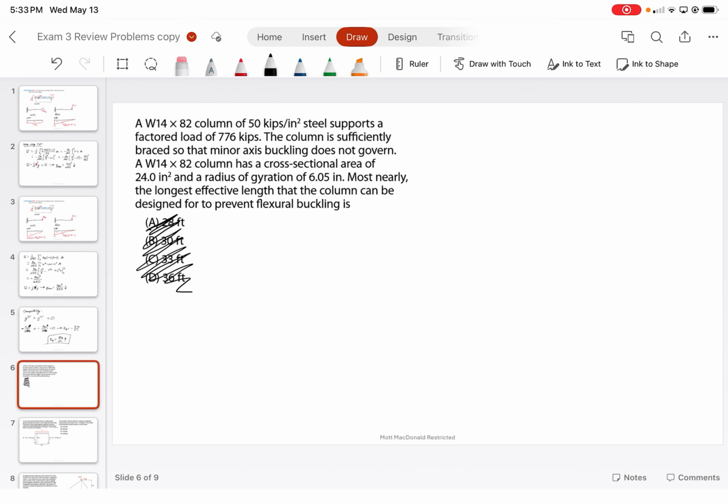But still, that seems very low, the K. I don't know if I switched that in the wrong place. Area was 24, radius was 6.05, so 6.05 squared times 24 got me 878.46. That's your issue. What's the equation for critical buckling?